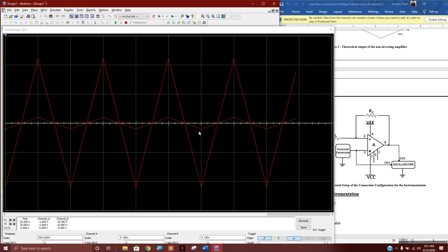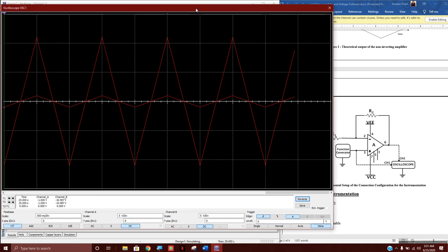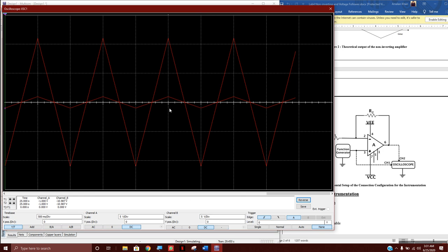And exactly the same way, no wait, let me just see this. That is 5 volts per division. So this is one division, this is two, that's 10 volts, and that goes over. So that means 1 volt and 1. Okay, fine. So you see, here we have a gain of 10. We provided 1 volt peak to peak, which means 1 volt up and 1 volt down. We have a gain of 10, however you like to say it.